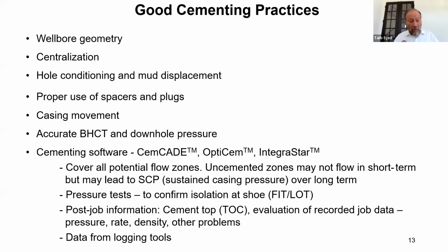So it's very important to cover all potential flow zones. Uncemented zones may not flow in the short term, but may lead to sustained casing pressure over the long term. Pressure tests, post-job information, and data from logging tools.